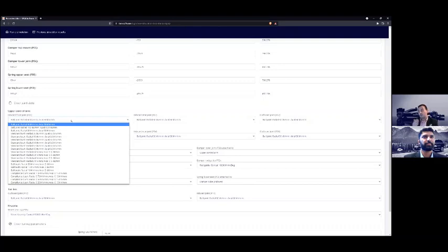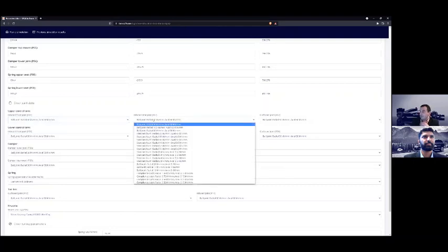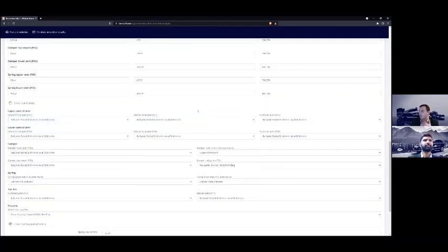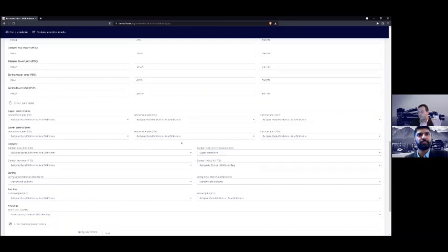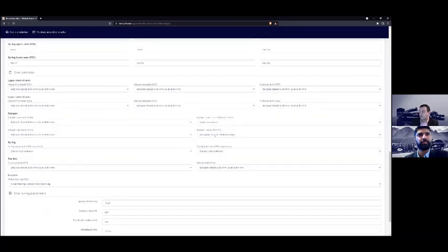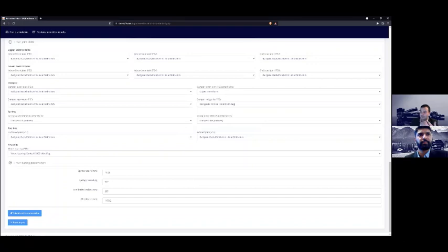The standard level offering, it's like a Pareto approach 80-20. Besides being able to specify the stiffness at each pickup point, you also have full topology. So you can attach the damper to the lower control arm, upper control arm, or to the knuckle. In this case, it's to the upper control arm. You can also specify your rod guide stiffness, your wheel bearing conical stiffness, and after that you enter your tuning parameters, the spring weight. For the purpose of the demonstration, I'll just change it to something else, and also the spring preload, the tire loaded radius, and the wheelbase.